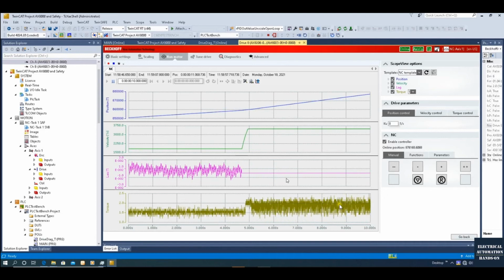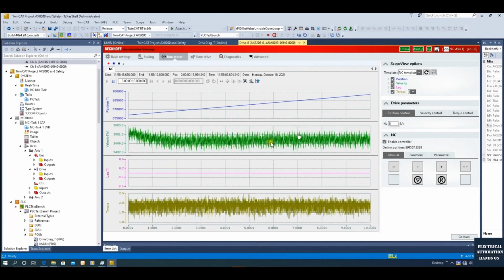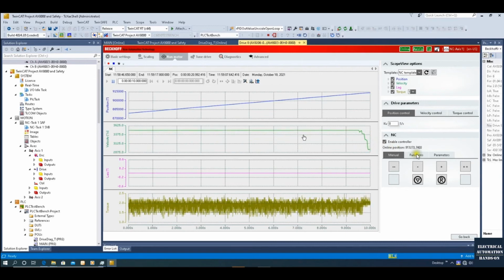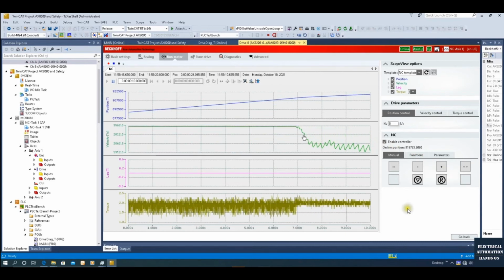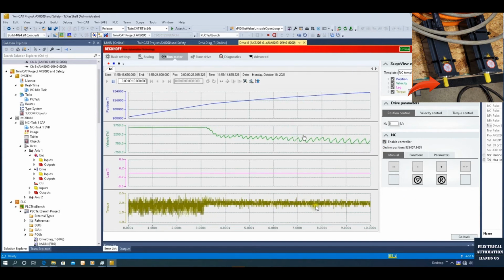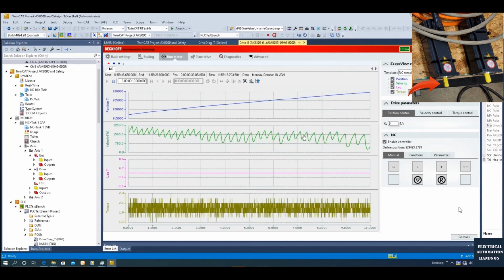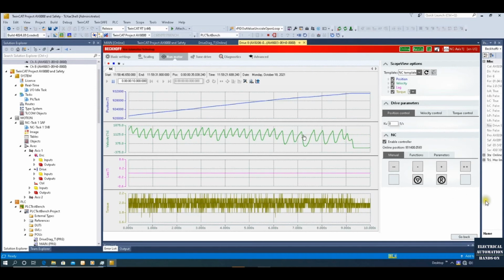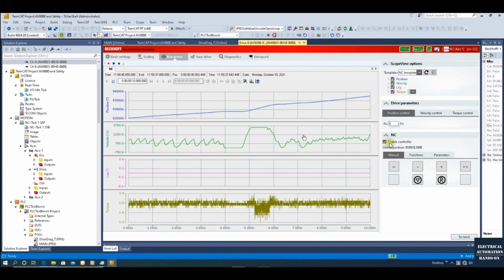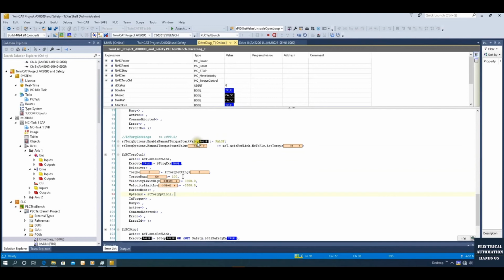Okay, we can see the torque value are set to 2. This 2 delivered into the system. And now the speed will be very high, reach to the high limitation, 3500. Okay, if we hold the shaft, velocity decrease, but the torque still at 2. Okay, because we are going to control the torque at 2%. The speed limitation is just a high limitation, but the actual speed depends on the actual load. But the torque, the highest torque will be 2%. Okay, because the set point is 2 here.